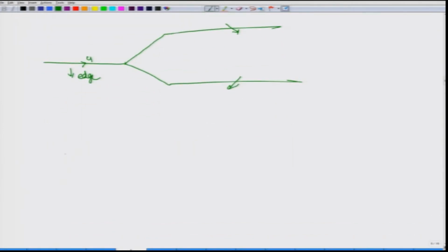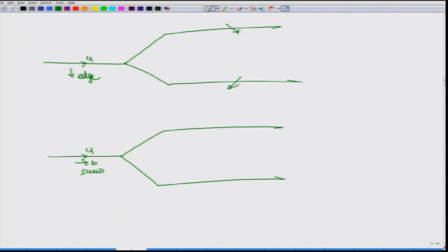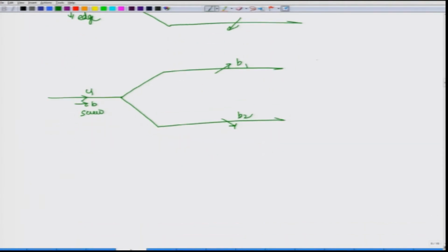The question is whether you will get a net repulsive force when you are talking about a dislocation with parallel, that is screw character. So, this is now screw, and in the most general case, like I said, partials will be mixed character.